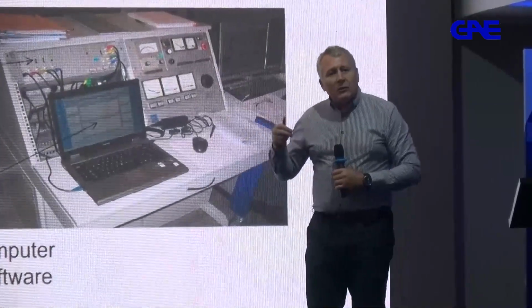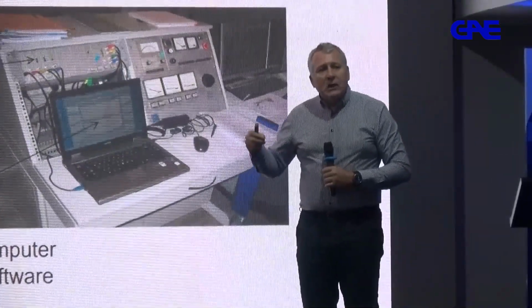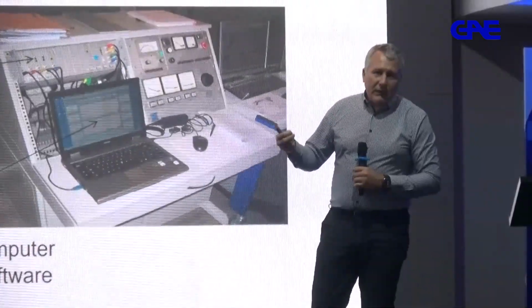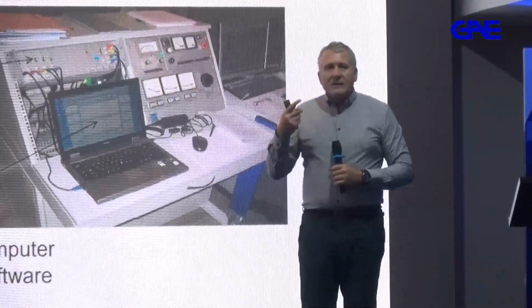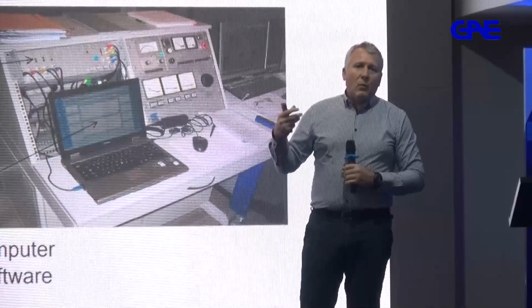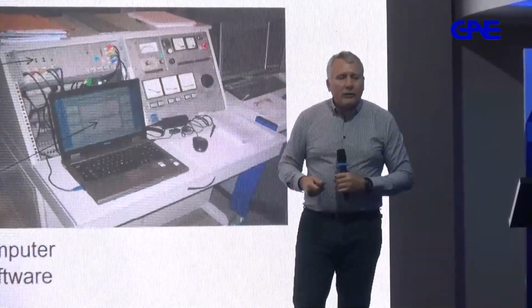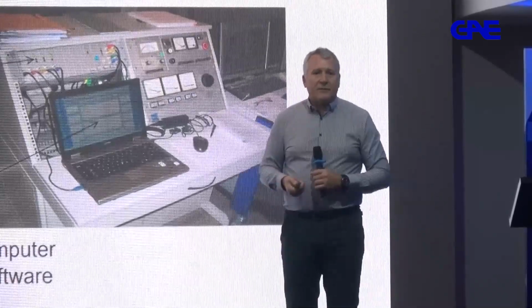Now, you can understand that everything I'm telling you now, and I'll show you towards the end of the talk, can also be determined online. So you can ask yourselves, being a power utility or a company that has such transformers in their exploitation, okay, so nice, I got a good transformer one day from the factory. How does this transformer evolve over time? And basically, again, monitoring for partial discharge becomes a very interesting topic.